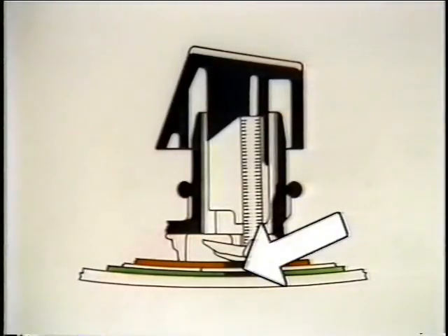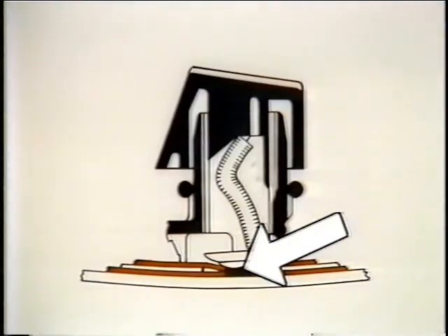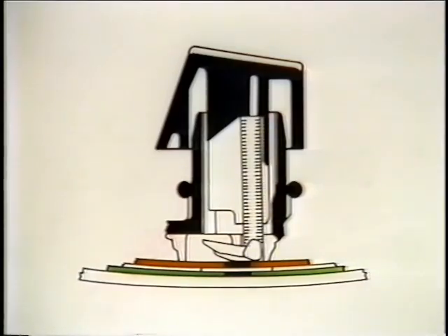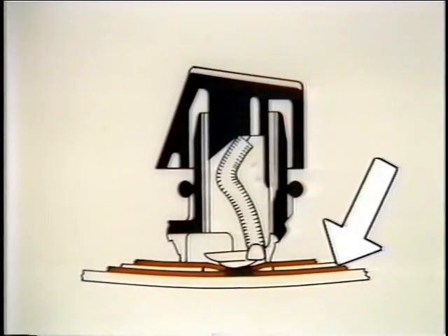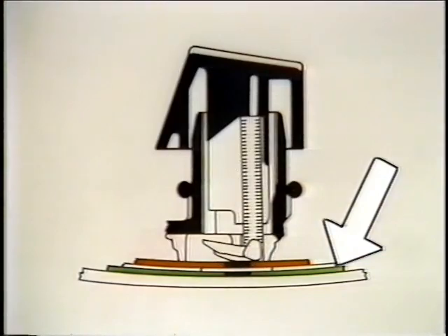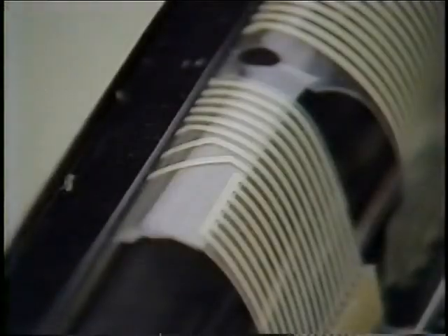When a key button is at rest, the membrane switch is opened. When a key button is pressed, the contact point on the sense line presses against the contact point on the drive line, closing the switch. The function board, which supplies 5 volts DC to the sense lines, scans the drive lines 76 times a second, looking for a closed membrane switch. When the membrane switch closes, the 5 volts DC is applied from the sense line to the drive line. When the function board scans the drive line, it notes that the switch is closed and sends the appropriate instruction to the printer board.